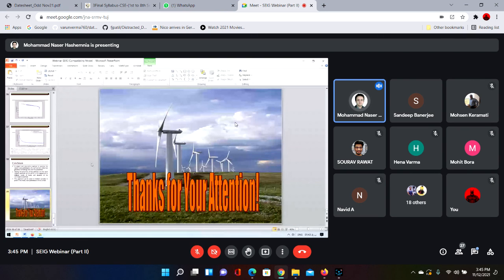Then you can use them as induction generators. Of course, I know maybe you mean that the optimized induction generator can be different from optimized induction motors, but this is out of my scope. My scope is not electric machine design. I assume that we have an induction motor in hand, then we want to use it as an induction generator. If we have the parameters of that induction motor, then we can calculate the capacitance value, which leads to the generating mode of operation.